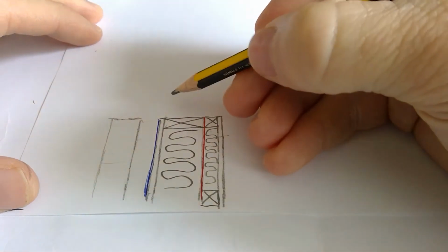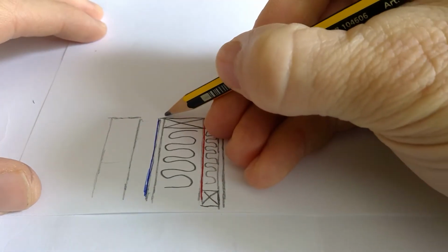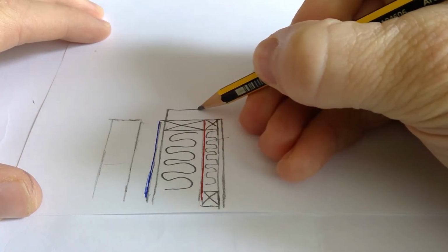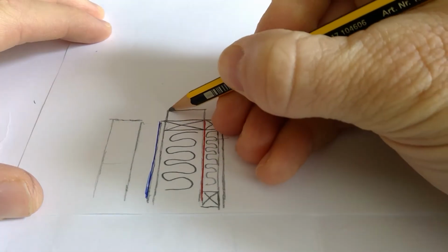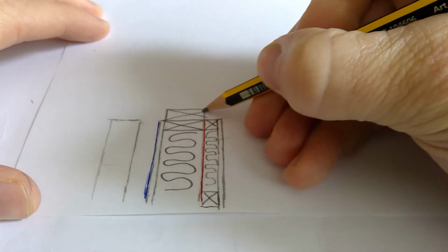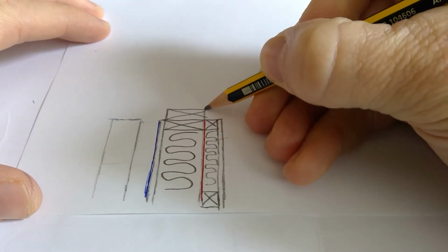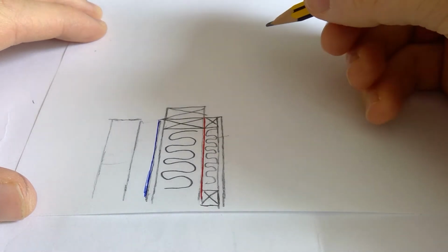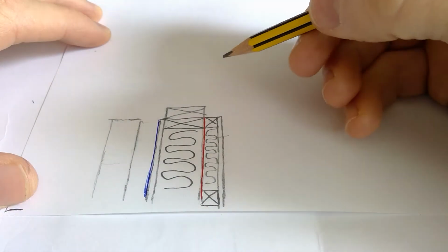Now we're going to start drawing the roof. We said it's a prefabricated truss roof. On top of this we have a wall plate. A wall plate with a timber frame roof is just a little bit smaller than a normal roof. It's just another head plate on top there. That's 50 millimeters by 200 in this case. All right, now next we're going to have the truss resting on top of that.